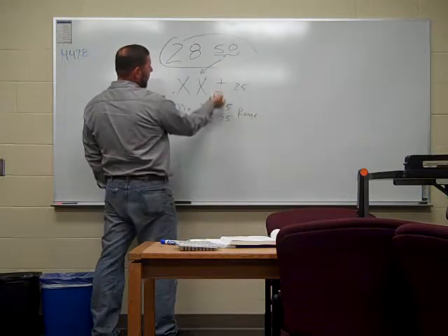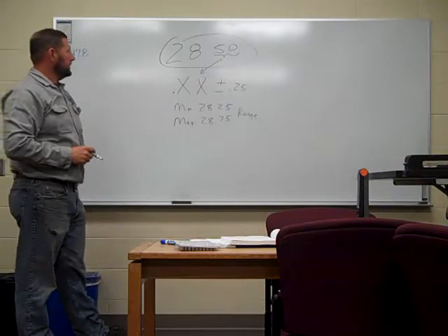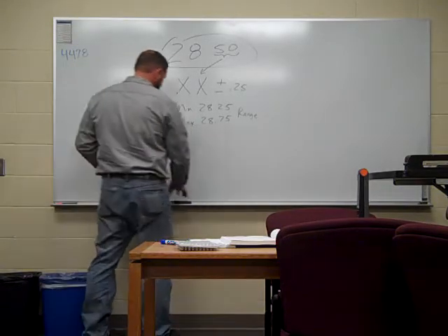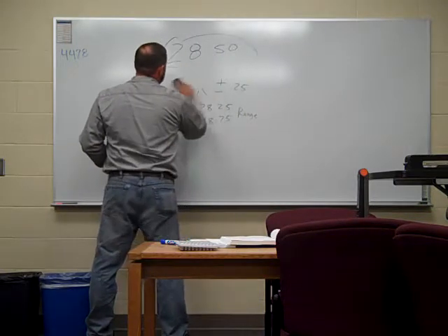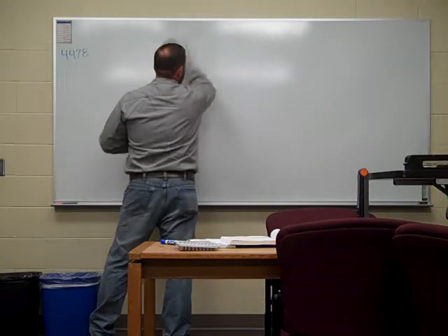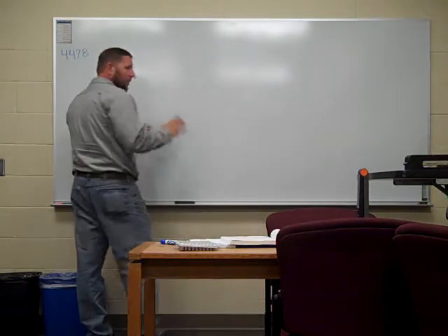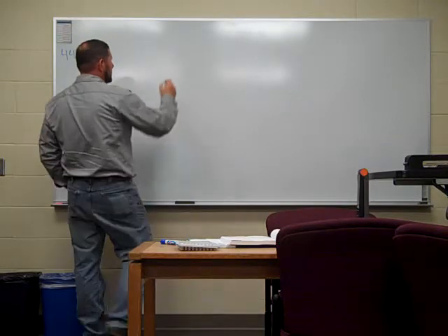It's plus or minus. Now, let's add a decimal place. That's 2 decimal places, as you can see. Follow that general tolerance. That applies to all dimensions on that print with 2 decimal places.